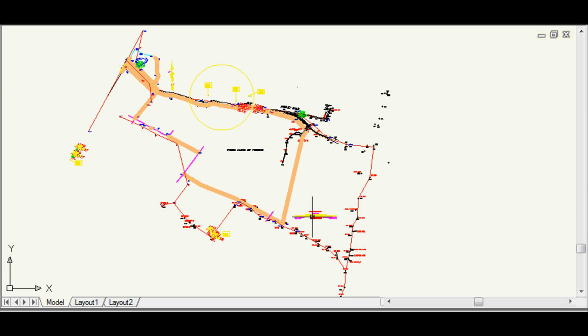And because of that, if we run the loop and we measure each of the angles in the loop, and as you saw, we measured those angles multiple times from multiple setups ultimately, once we've done that, we can calculate what the total loop closure is, and we can calculate what it should be, and then we can calculate what our error is. And that gives us a controlled loop, basically, a way to control the angles and lock this in as something that we can count on as a way to take measurements from.